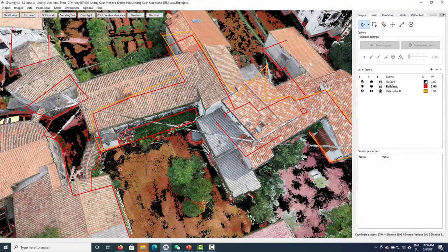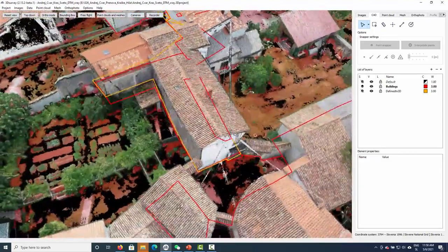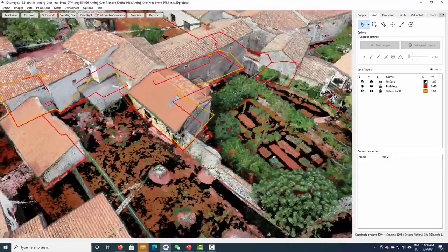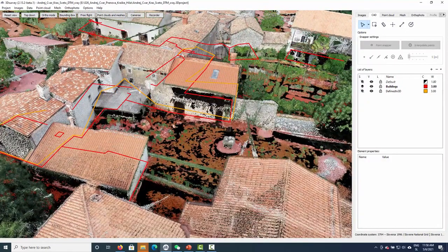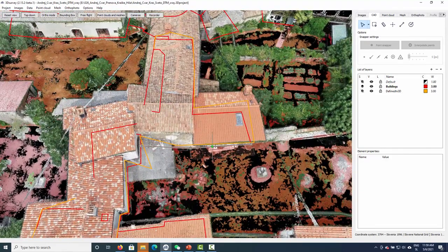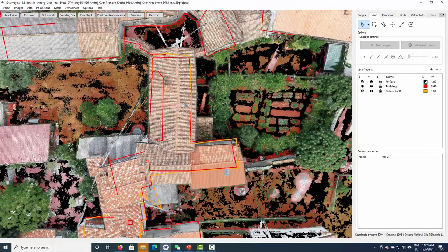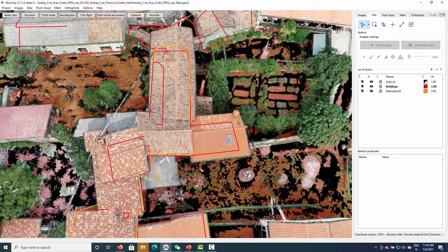So this showcase that I am showing is actually from a real world example. So we were actually mapping this area before we had the X-ray function. And what's interesting about this one is, for this area we also have some prior measurements that were done by a third-party land surveyor, who was doing this for the company that contracted also us. So what they did, they measured these courtyards here also with the total station. And what we can do now is we can bring in those measurements and we can compare the difference between the outlines that we defined and outlines that the land surveyor defined using total station.